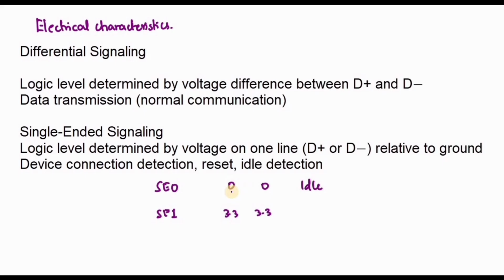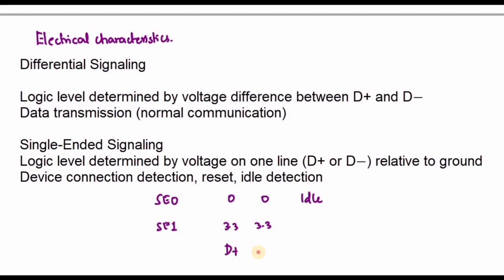The ground is always common to all devices of the computer. Signals sent by one device can cause a small variation in the voltage on the ground wire, and hence can interfere with the signals sent by other devices. This interference is also caused by one wire picking up noise from a nearby wire.